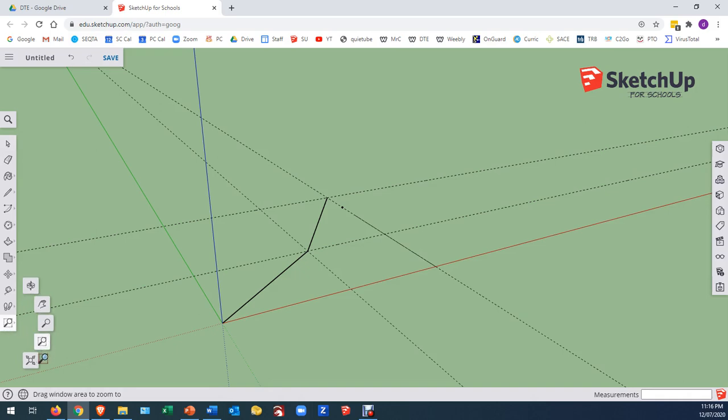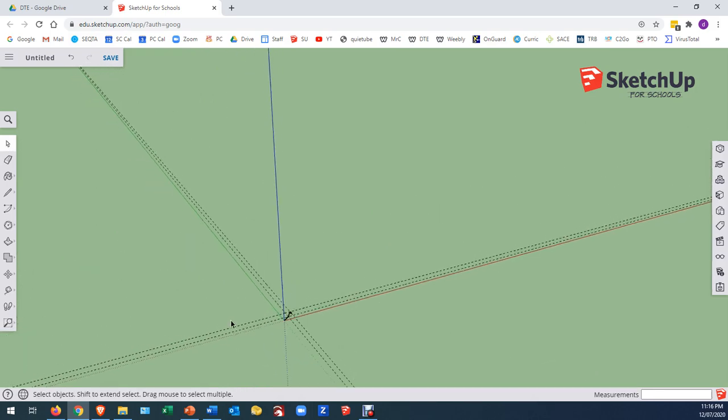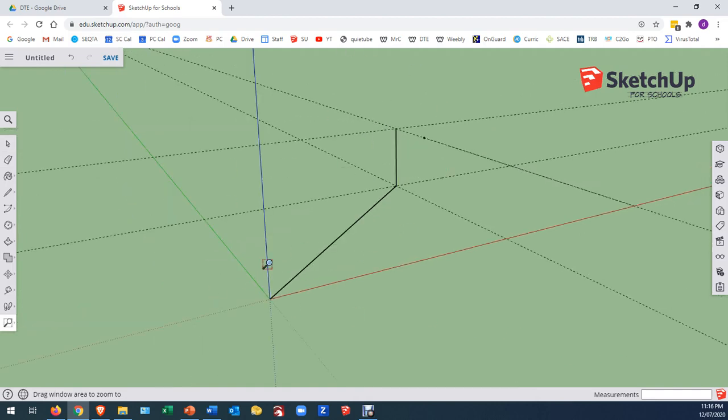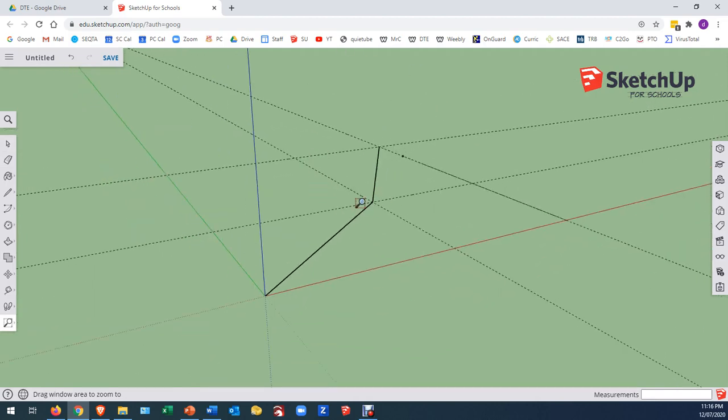The one that is definitely useful at all times is this one here, Zoom Extents. Now, once again, I'm going to show you that if I've zoomed all the way out here, if I wanted to not zoom around here, but I just wanted to bring in, I can come here and I can click Zoom Extents, and what it does is it basically fits this into the window. Sometimes it makes it a bit bigger than you need it, and you have to scroll out a little bit, but this actually gives you this picture here. When you're working with three-dimensional shapes and you sometimes land up inside the shape and you don't know where you are, the Zoom Extents is a really, really good way of stepping back, seeing the whole shape, and then being able to manipulate yourself around it.